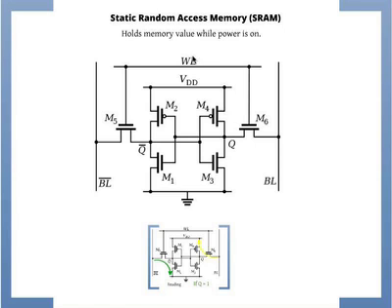Okay, let's do it again. Q bar is 0, because Q is whatever is stored there. I'm just saying it's 1 for the sake of argument. Q is 1, Q bar is 0. If Q bar is 0, look at transistor M4: it's PMOS, and it's on. Now I turn on the word line, so M6 is on. M4 and M6 being on means that this circuit is complete.